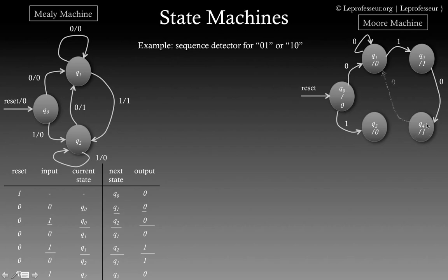Now it can also happen that after detecting 1 0, we are in Q4 state and we find 0 at the input, so we go back to the Q0 state and stay in this state until we detect 1. Or it can also happen that after detecting 1 0, we are in state Q4 and we receive 1 at the input, so we go back to the Q3 state. Similarly, we can complete this state diagram, right?